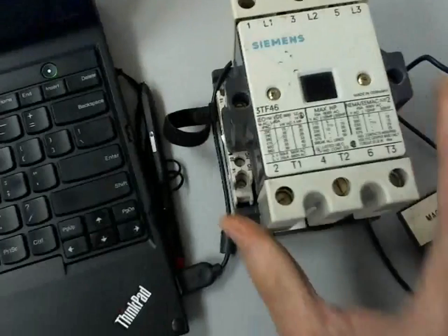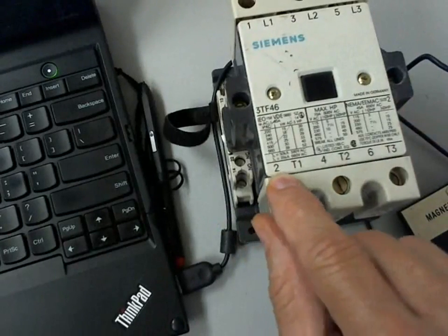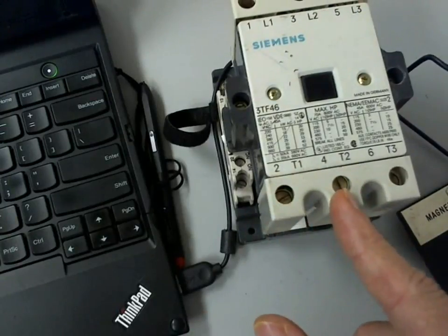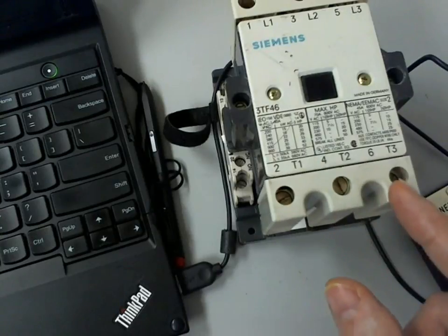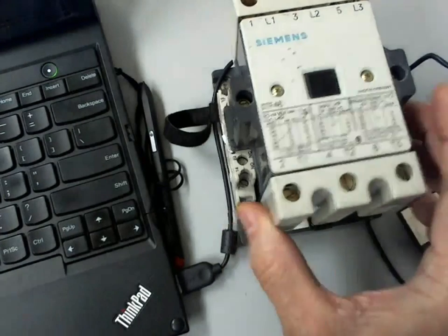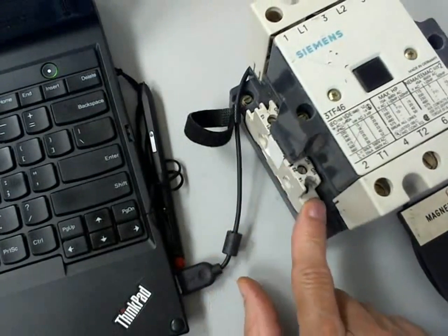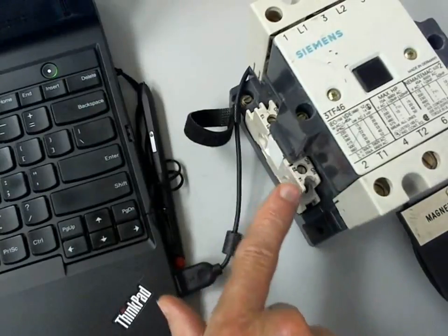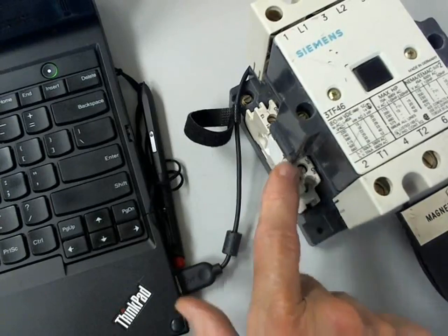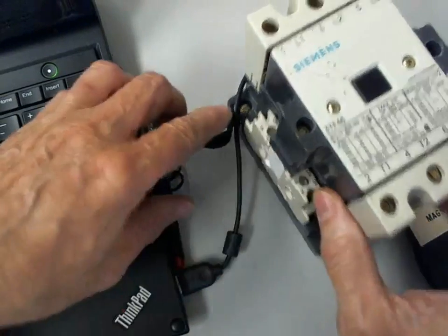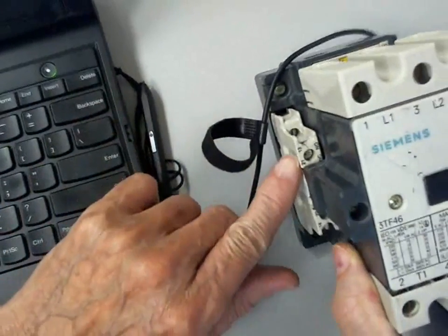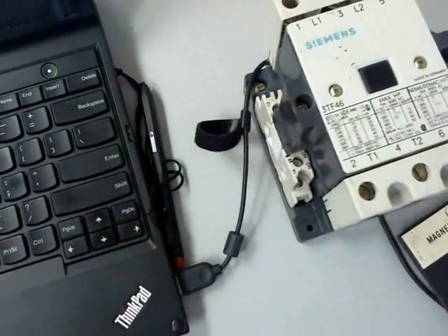Understand? Then I come down to this side, and they got what? 2 and T1. So that would be this contact right here. This is T2 or 4. This is T3 or 6. Now, who did these? And even if I look down here, we see this has 2 contacts on it. It says one in the bottom, one in the top. So this bottom would be 14. This right here would be 22. Over here, the bottom terminal would be right down here. This would be 13, and the top terminal would be 21. Now, how did they get on there?